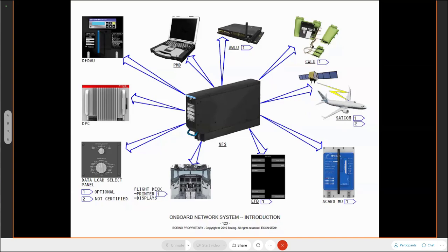Okay, a lot of aircraft have a standalone QAR, whether it be an optical drive, some kind of device like that. You can still get a standalone quick access recorder for the MAX. It's just that that is no longer standard. The network file server provides that capability now.